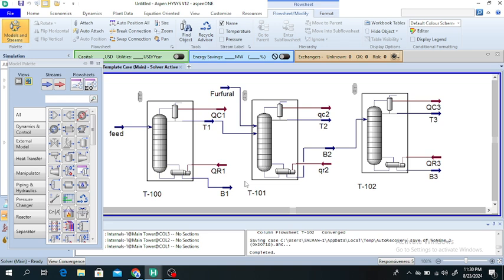in an extractive distillation column. So here you can also obtain the condenser duty. Suppose the power of the condenser is 4569 kilowatt. The reboiler duty for column 1 is 5241 kilowatt, and the power of the condenser for column number 2 is 4489 kilowatt, and the reboiler power for column 2 is 5073 kilowatt. The condenser power for column 3 is 2754, and the reboiler power for column number 3 is 2787.